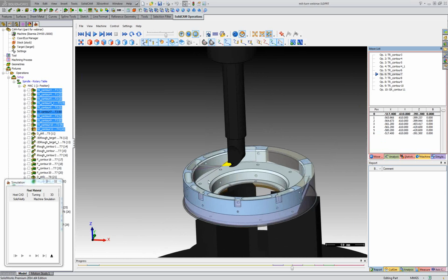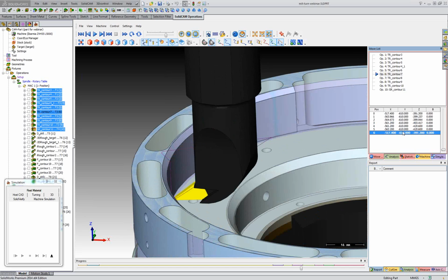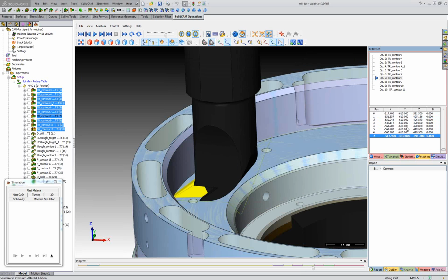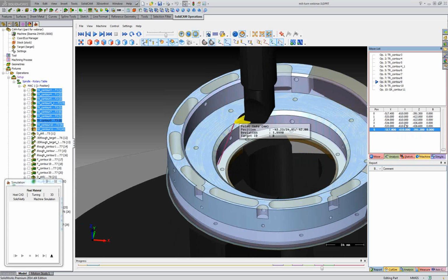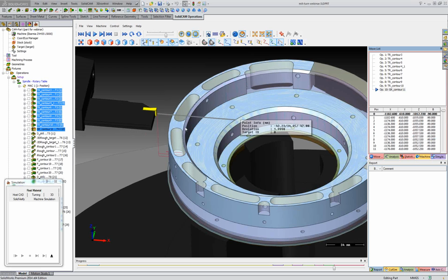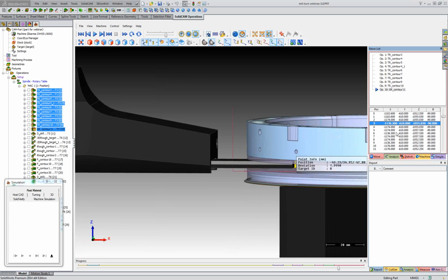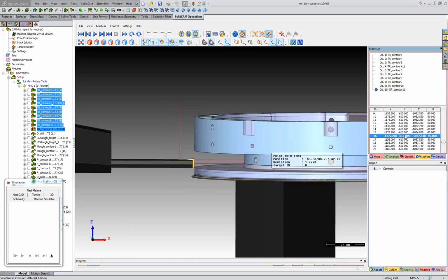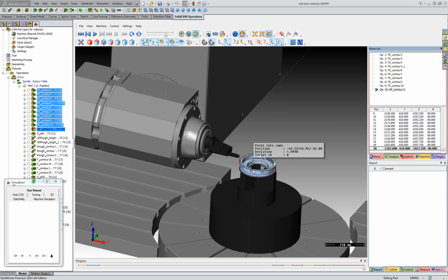Internal turning now. For finishing, I finish first as we define the chamfer and this diameter with a retract. Now this chamfer and the floor inside outside, always with a retract to a safety position. Go down and finish this diameter and the floor. Grooving operation. Let's see. 1, 2, 3, and the finish on walls. It's a down-only finish technology. That's all. We finished the turning process on this part.